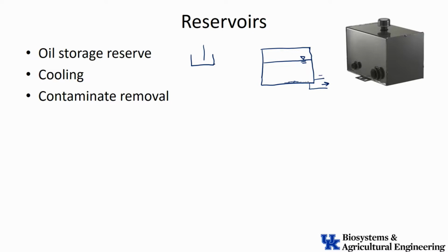I've got part of the tank that is going to be below my pickup that I'll never be able to use. I'll actually never be able to pull out of that, but you can see it on the side here. So this big port on this tank is on the side, but there's a little bit of space below it, so I don't drain it completely. I'd have to put a plug on the bottom then of some kind to be able to drain the tank, to be able to change it and clean it and so forth. But that's where my pickup would be.